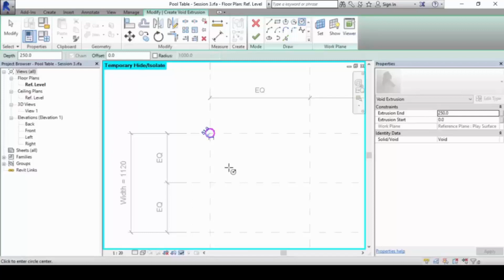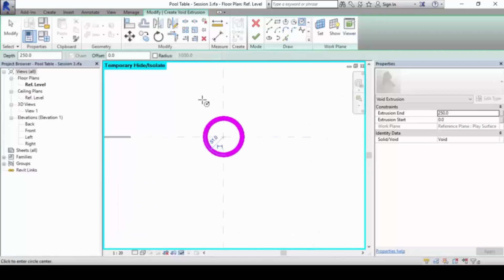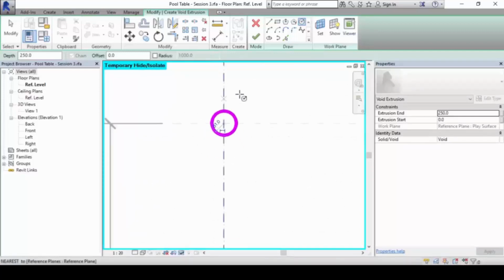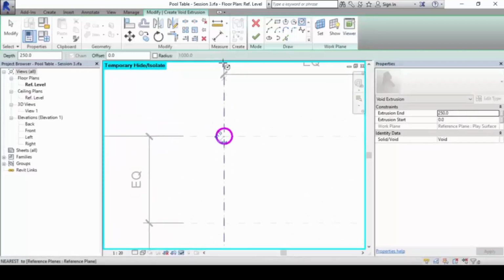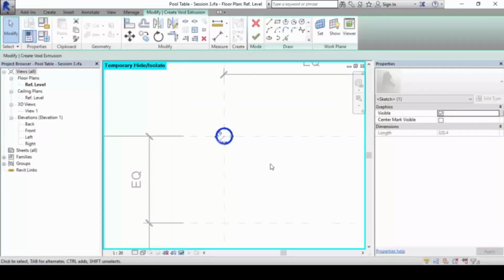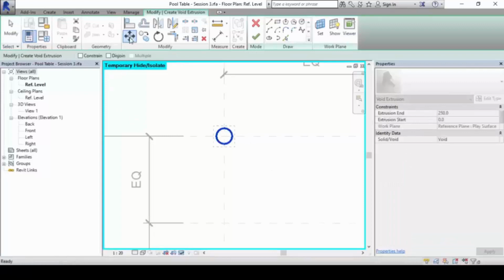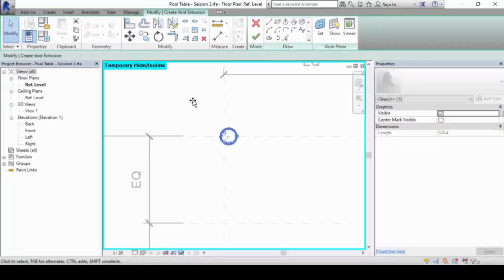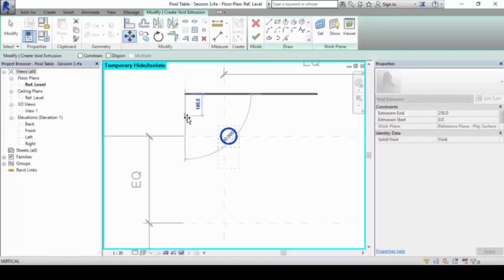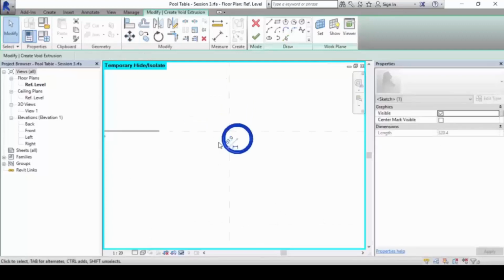When done, we are going to shift the location of this circle. We are going to do that by selecting the circle first, then issuing the command. We move x-axis by 29 and then the y-axis by minus 29 this way. So it looks like that.